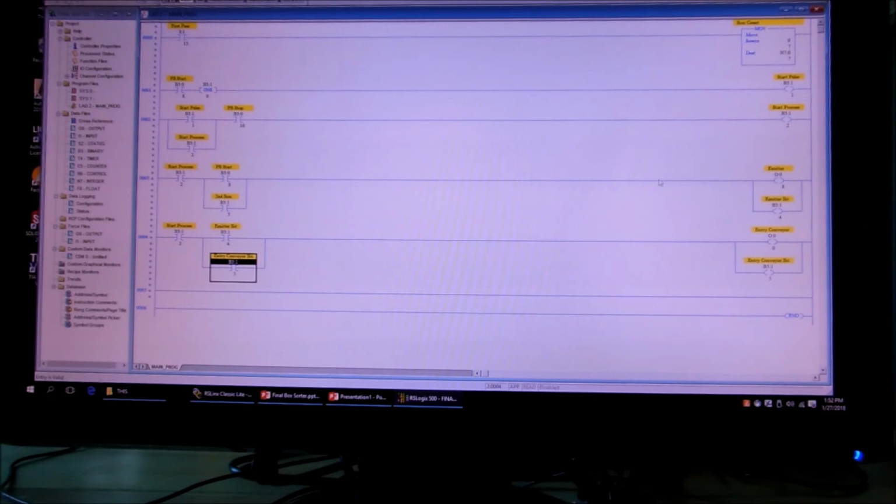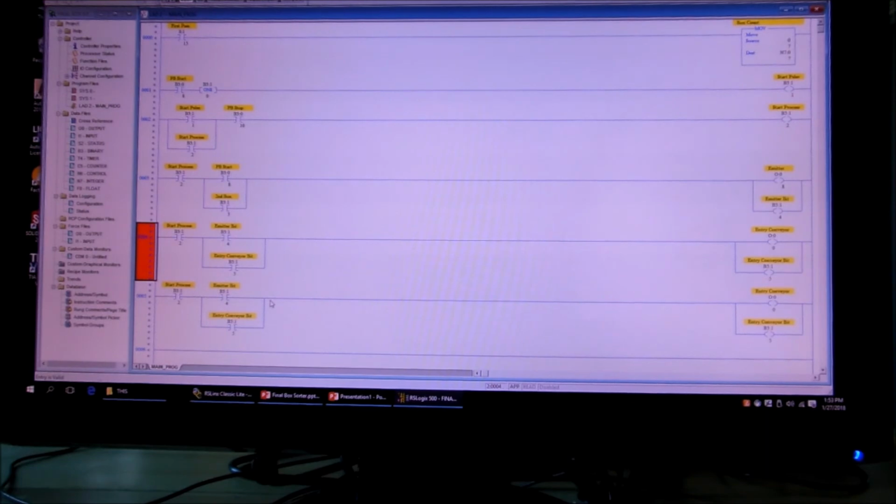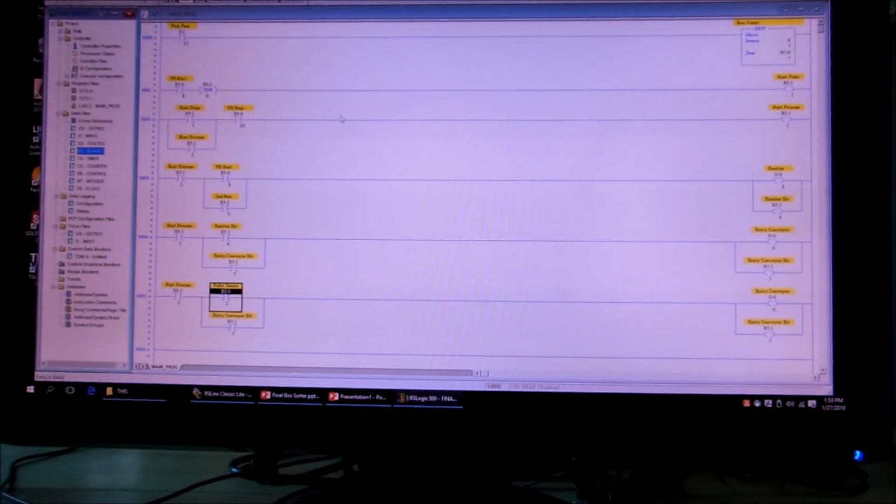So now we've got the emitter turning the conveyor on. We'll do the same thing. This is all just a big copy and paste, and after we do this one, I'll give you guys a break, and then we'll come back and you can see the finished product. Now we've got the entry conveyor moving, and what we need to do is get that load signal moving. That happens when our pallet sensor senses the pallet.